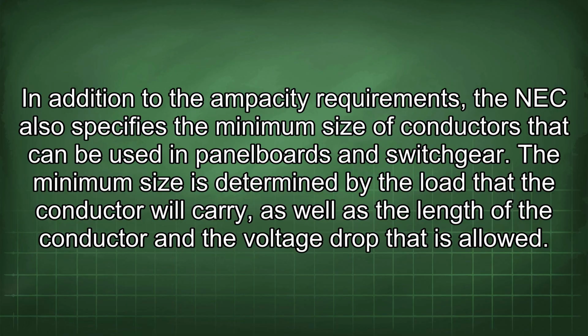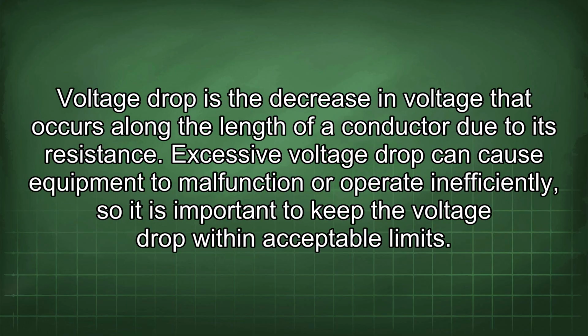The minimum size is determined by the load that the conductor will carry, as well as the length of the conductor and the voltage drop that is allowed. Voltage drop is the decrease in voltage that occurs along the length of a conductor due to its resistance.